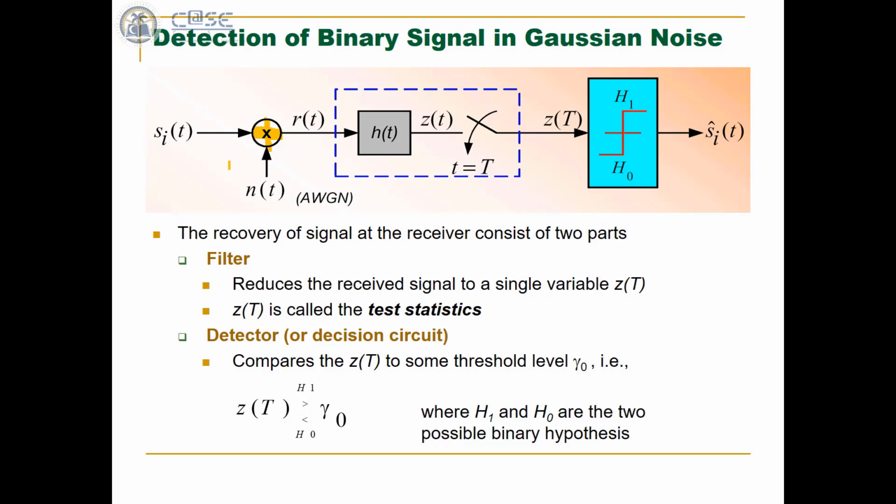If we have, say, 32 possible signals, then we would have 32 matched filters as a result, matched against those possible copies. So this means we have a scenario in which the complexity of the receiver block may increase with the number of possibilities at the transmitter end.